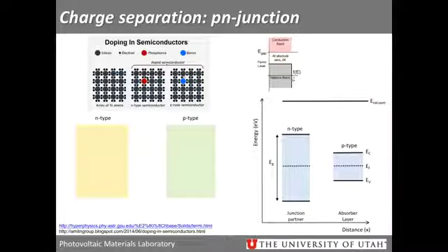Okay, so briefly about pn-junctions, which are kind of the backbone of inorganic photovoltaics. This is true for silicon or gallium arsenide or CdTe. Any kind of solar cell uses these pn-junctions because, I'll talk about it, but because of charge separation. So when we use two different types, an N-type and a P-type, have you guys talked about pn-junctions? Okay, so with pn-junctions, we can have an electric field that will separate electrons and holes